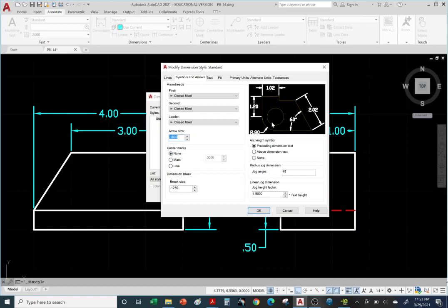If you want to add a center line, when you add a radius or diameter dimension, it can insert a center mark, as you can see, and you can even extend it if you pick the line option. We are in the Symbols and Arrows tab. We'll be doing this later on in a separate problem that has a circle or an arc. You can just say none, and it'll just put a little dot, which is part of this radius dimension. It also allows you to change other things, which typically you just leave alone. You want to follow a standard.